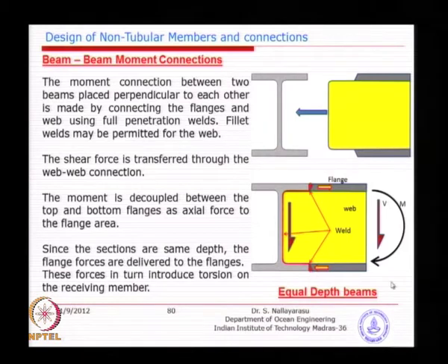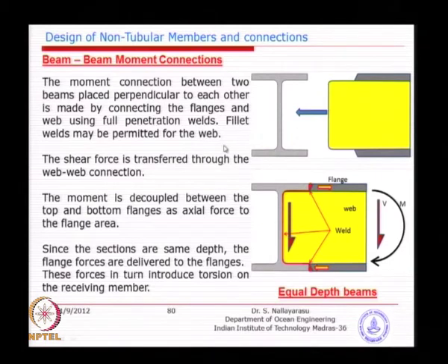Now, when you apply a vertical load, which is coming as a shear and also a moment. So, you could see here how it will actually develop. Shear will go as a perpendicular member to the web as a shear. Of course, you have a redundant welding here, that will not be too effective, because most of the load will be taken by the vertical weld, which is very stiff compared to the top and bottom weld.